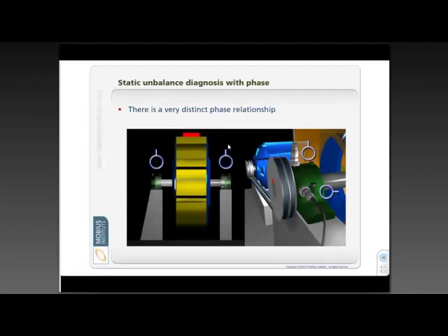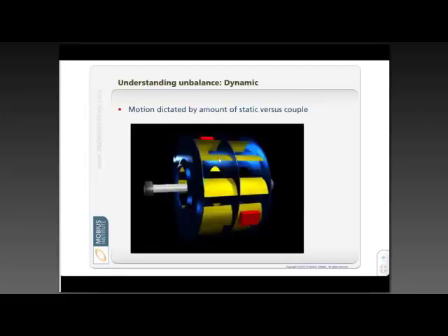The little stick at the top just tells me that from this side to that side, they are in phase. I could write down the actual measurements that I took, but the main thing is this just tells me they are in phase. You can see there's two over here, one up, one at 3 o'clock, 12 o'clock and 3 o'clock. That's 90 degrees, and that would tell me again that it's unbalanced. So this tells me it's unbalanced, this tells me it's statically unbalanced.